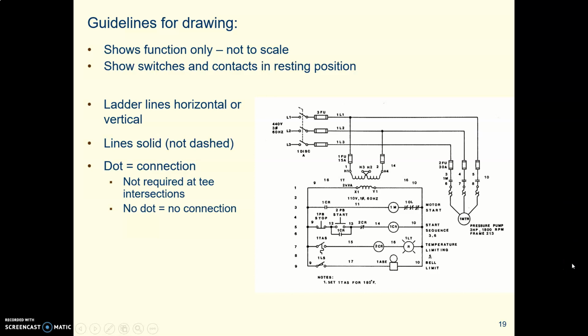Now, when you're drawing a ladder diagram, remember, we already talked about this, but we are not drawing anything to scale. We are just showing the function of the circuits. And we are always drawing our switches and our contacts in resting position. Either they're normally open or they're normally closed. All right, so other guidelines.